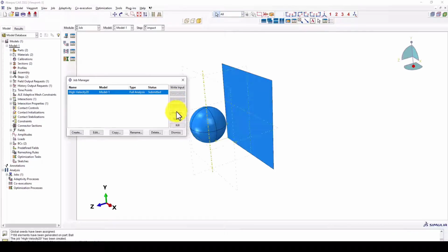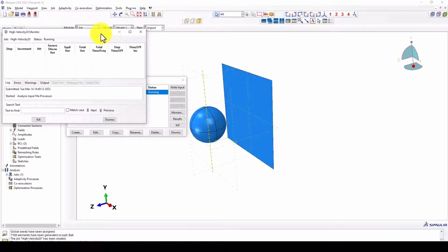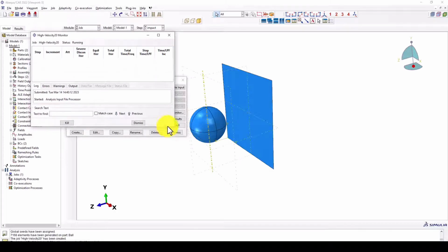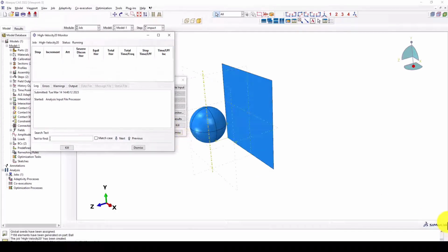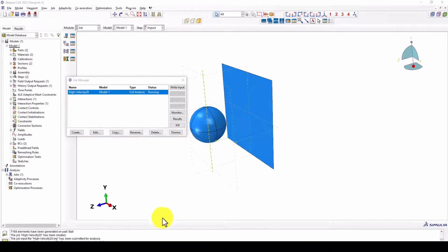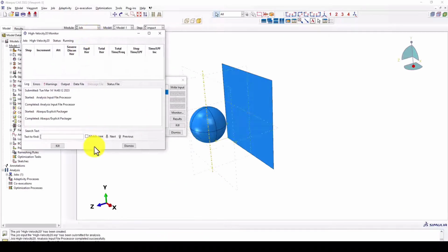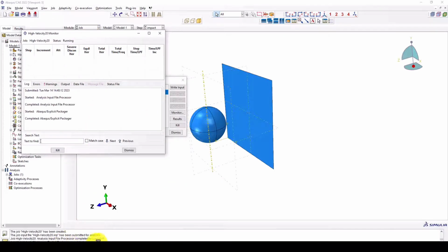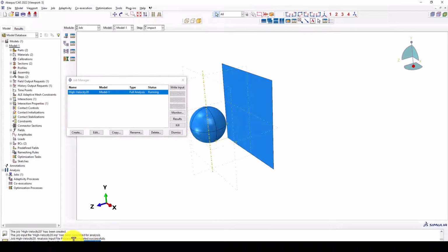plastic material data is also required. For a basic elastic material, we need to define Young's modulus, as I told you, and Poisson's ratio for the basic requirement. But for impact analysis, don't forget density. Density is not optional in a dynamic impact problem. Abaqus needs to calculate the inertia and kinetic energy.